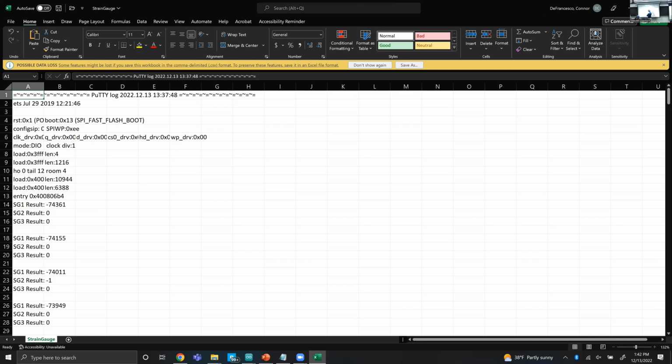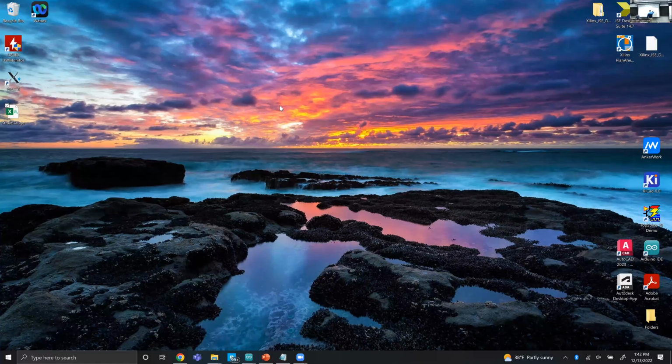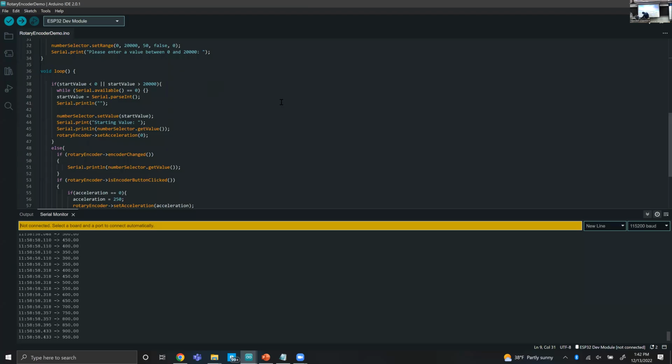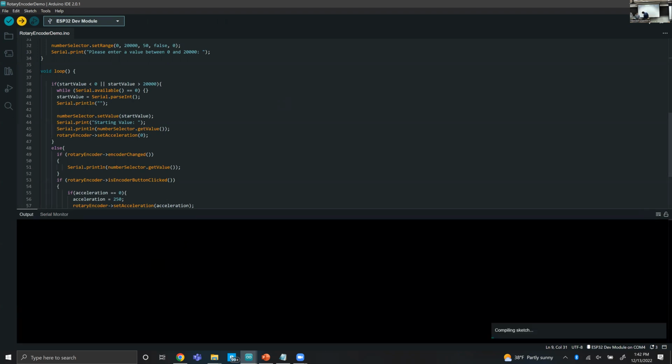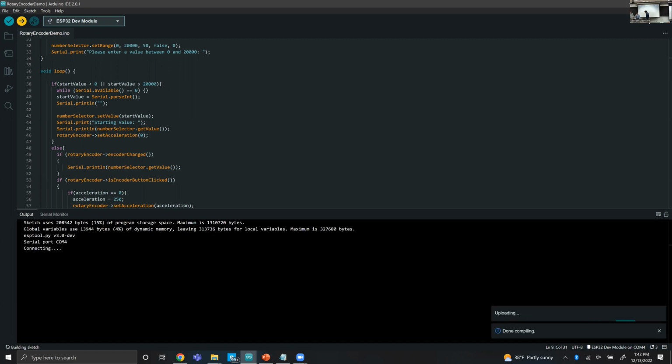So this has the amplifier. Without the amplifier, would the numbers be so close that you would not recognize the difference? The whole point of the amplifier is that you can't plug these wires directly into the ESP32, because this is just measuring voltage potential, and the ESP32 doesn't have the capability of reading that. This is the amplifier. What is this? That's the accelerometer. We just didn't take it off. Well, that's a better implementation than this one. Yeah, it had the pins already.